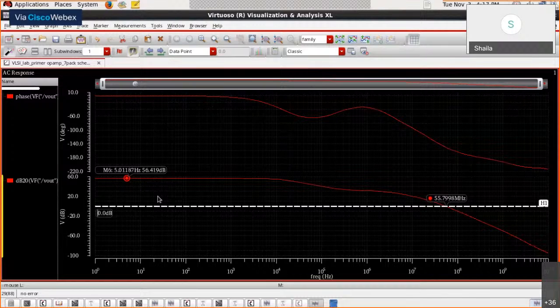Doubt in the sense, is it a thumb rule to keep L equal to whatever is the technology parameter for analog devices? No, madam. If I need large gain, then I actually require a larger value of rout for my active devices. Therefore, I choose larger values of L. So L can be 2.5 times the minimum or 5 times the minimum.